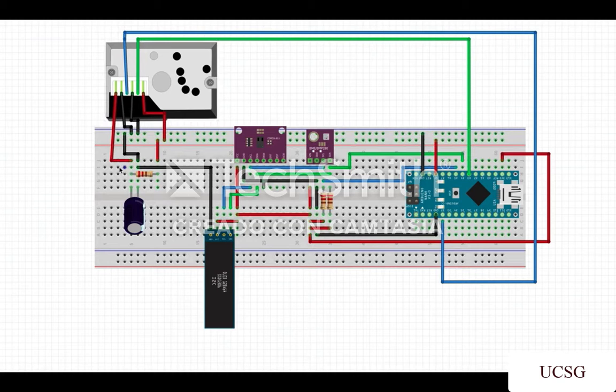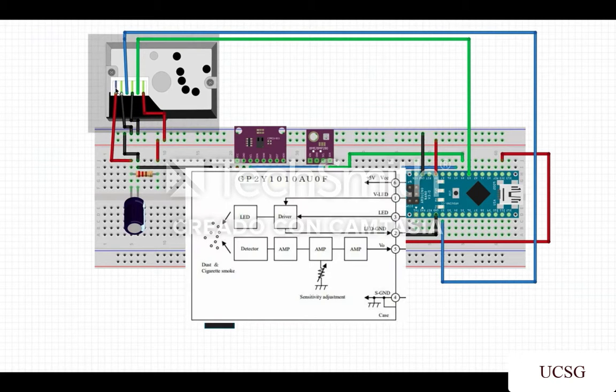The sensor has 6 pins. The first one is the VCC pin and is connected to the 5 volts through the 150 ohm resistor. The second one is the LED ground pin, connected to ground. The sixth one is the positive supply pin connected to the 5 volts of Arduino. It's a simple VCC, the first one and the last one. The resistor supplies the sensor and the capacitor.